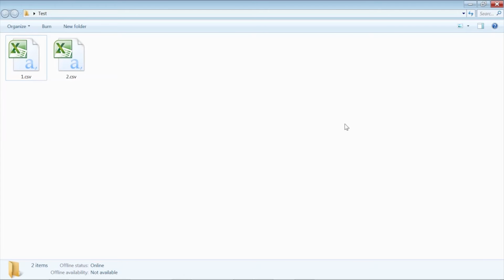I'm going to show you how to process data which you have received from the test on Instron machine. In this case it's going to be a tensile test where you have loaded a sample to very low strain and then unloaded it. This test is usually done to measure initial stiffness of the material, as well as initial Poisson's ratio.